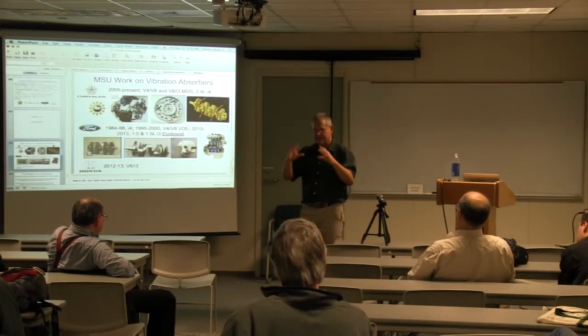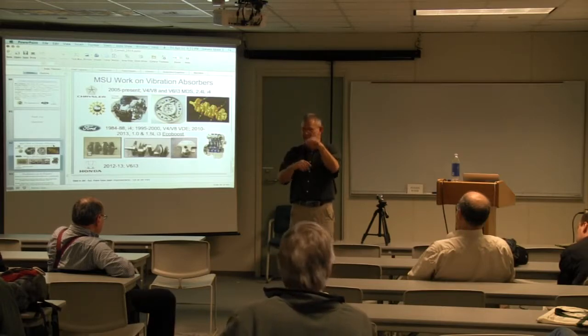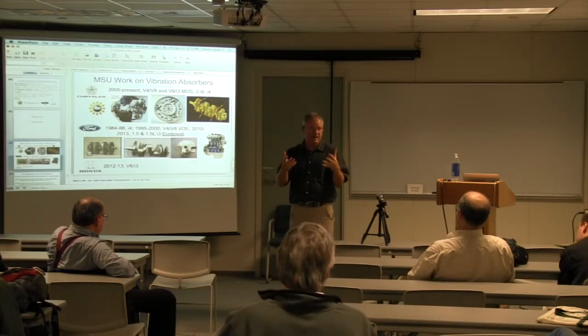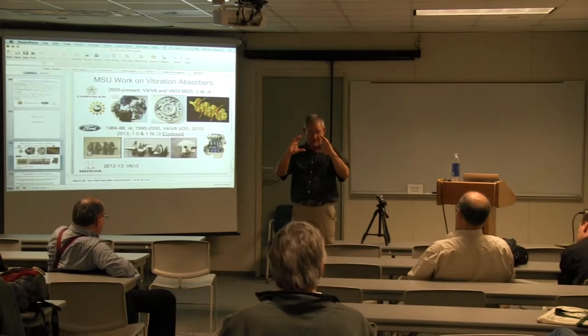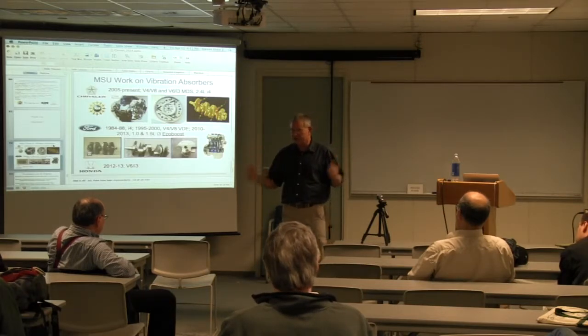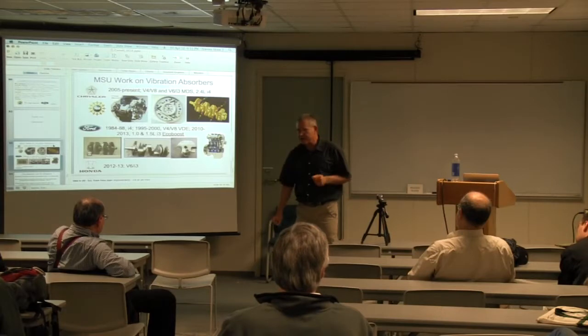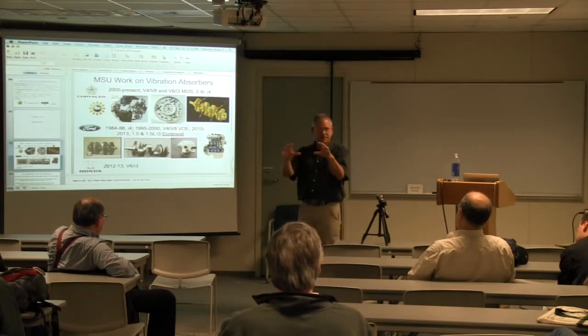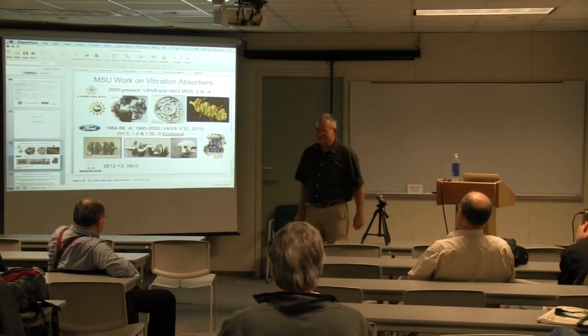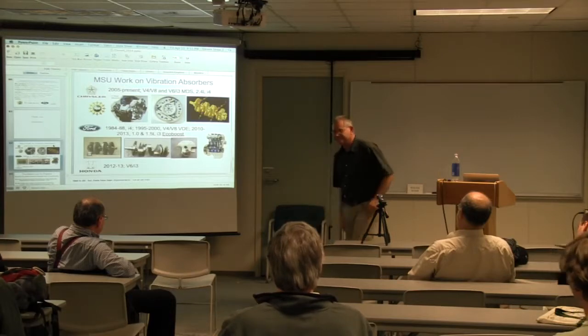But anyway, the point is that as you're changing all this, you're changing the center of mass, you're changing the tuning. So to design an actual mass and the cutouts is an iterative process. Bruce wrote a code that does that. He says, okay, I want a cycloidal path tuned to order 1.51, and this thing will evolve and come out with it, then he can send it down to the machine shop.